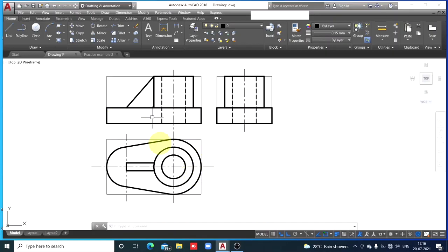Remember, in a view shape, in the remaining two views it appears as a rectangular strip. So in the front view it is a triangle, that is its largest surface, or you can say the shape of the plate. When you say it is a triangular plate, it means its largest surface is a triangle and that appears in the front view. So in the remaining two views this plate appears as a rectangular strip. So in the top view we have drawn that rectangular strip meeting the curved surface of the cylinder. Now we'll draw this triangular strip in the side view.